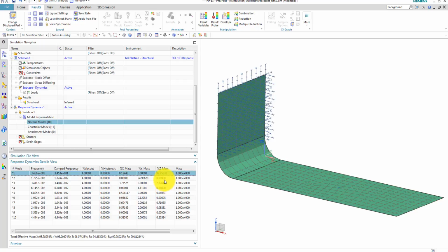Then we can neglect mode number 2, but mode number 3 is of interest. It contributes 2% of the mass motion. There are no other interesting modes, except perhaps mode number 7, but it has a resonance frequency of 1947, which is far beyond the excitation range that we will use in our simulations.